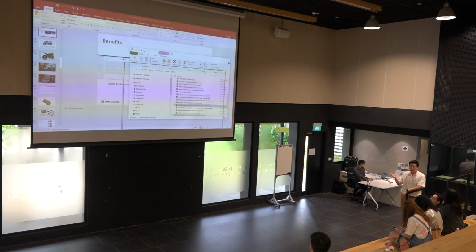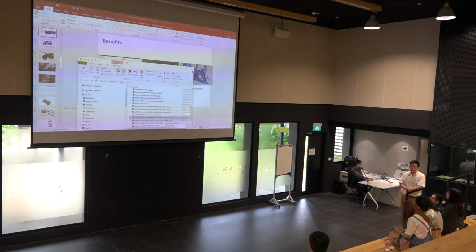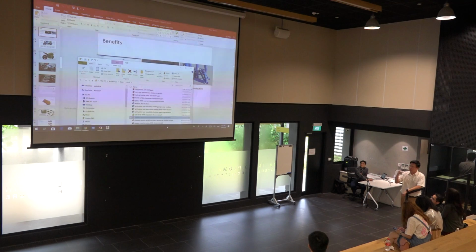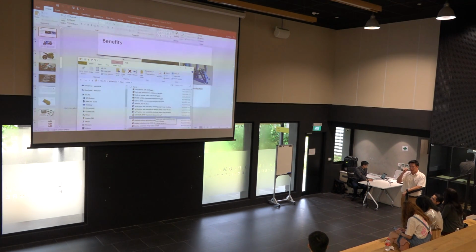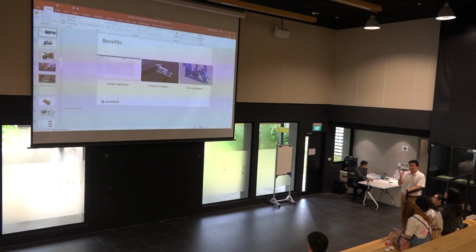Once you use Fusion 360, generative design is going to be a very complementary part of your design. With the design, you're fixing constraints, and after fixing constraints, you then use the AI function to generate it. That bracket, for example, can be a weight reduction of about, I believe, 43%. So from a lightweighting and optimization standpoint, it's about 43%. It's a really big part.